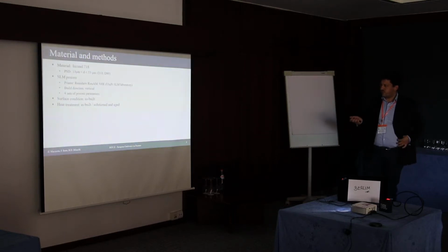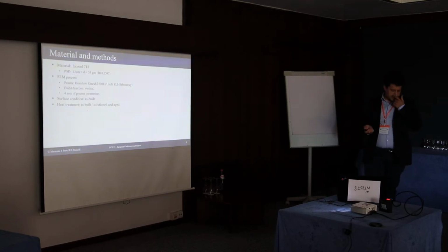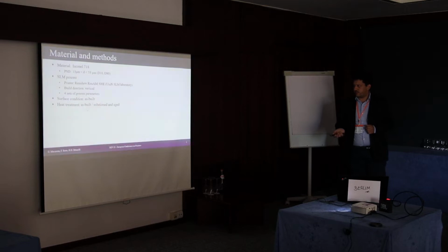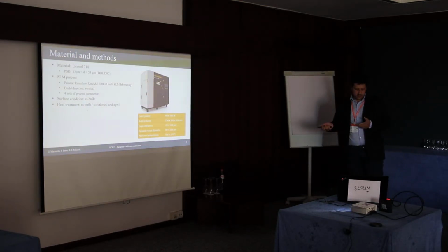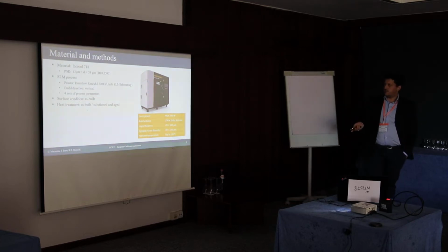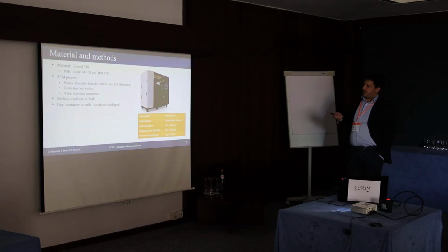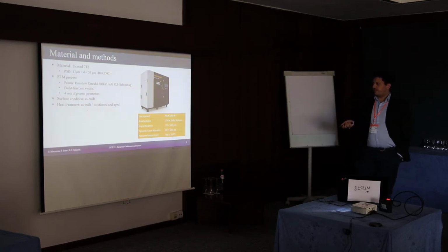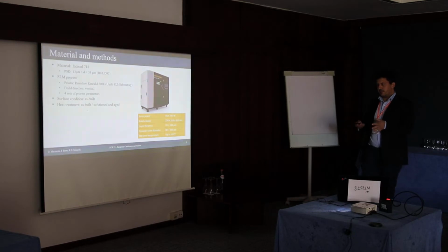So, the material. Inconel 718, with the standard powder size distribution that is used for the selective laser melting process. The process was carried out at the selective laser melting laboratory of the University of Pisa, where we have a Renishaw printer, the RenAM 500E, a newly introduced printer that has the capability of reaching 500 watts of power, and so it allows us to increase a bit the productivity and the power that we input in the process.